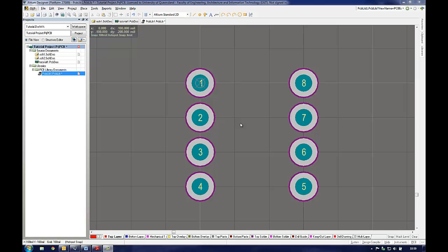Another hint is to make sure that the boundary of the component does not touch or cross any of the component pads. The clearance of the component body outline from the pad should match the default setting for the design rules. This will allow for simple soldering of the component to the pads. If any top overlay overlaps the solder pad, then this will limit the ability of solder to flow across the pad.